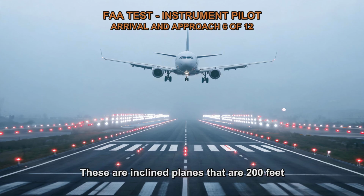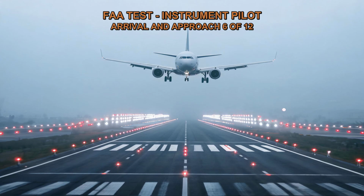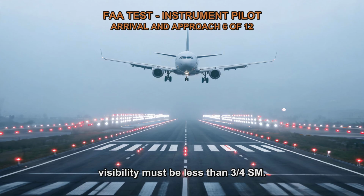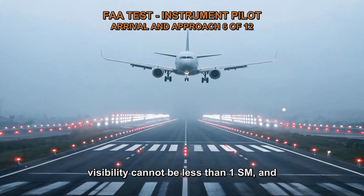These are inclined planes that begin 200 feet from the runway's edge and extend 10,000 feet away. If the 34:1 surface is penetrated, the published visibility must be no lower than 3/4 SM. If the 20:1 surface is penetrated, the advertised visibility cannot be less than 1 SM, and approaches must be forbidden.